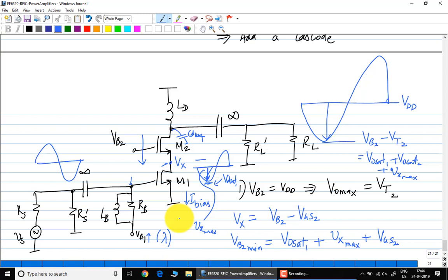No, the channel lengths are not available. They will not have 65 nanometers or 100 nanometers and so on. Gallium arsenide, I think you probably get like 120 nanometers now. Gallium nitride you can get about, I think, maybe 120, maybe 0.2, 0.25 microns. The technologies are lagging behind because you are building only PAs with them. You understand, right? So if you get enough power at the frequency that you are operating with, you are good to go.